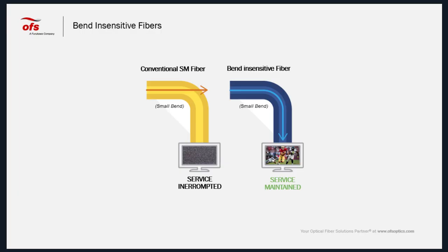You have seen that the process of fiber manufacturing is not easy. It's complicated. It needs a lot of skilled people to draw the fiber. So we cannot pretend to be a fiber producer overnight. It needs a lot of skills and a lot of knowledge. So from the start, from the VAD process to manufacture the preform, which is the origin of the fiber, to the VAD deposition, the sintering process, the drawing process, and control of the diameter of the optical fiber, to the proof testing of the optical fiber at the end of the chain.